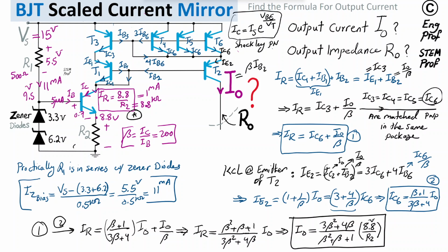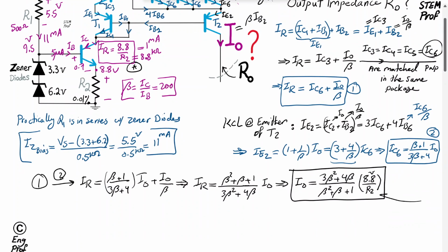Those resistors can provide 0.01% as low as that precision for the value of the resistor R2. So they are referred to as thin film resistors or precision resistors. So that's an option to have if accuracy of this R2 matters to us. So basically we have a good control on the value of R2.